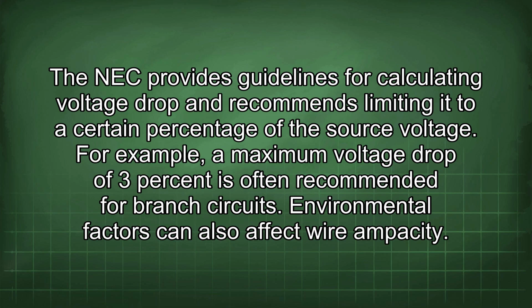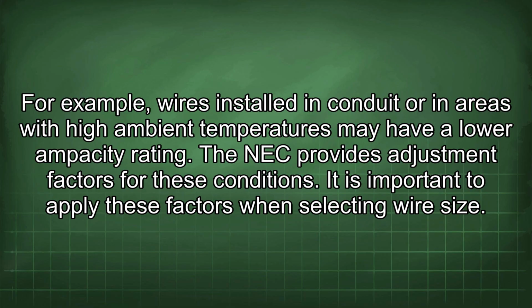Environmental factors can also affect wire ampacity. For example, wires installed in conduit or in areas with high ambient temperatures may have a lower ampacity rating. The NEC provides adjustment factors for these conditions. It is important to apply these factors when selecting wire size.